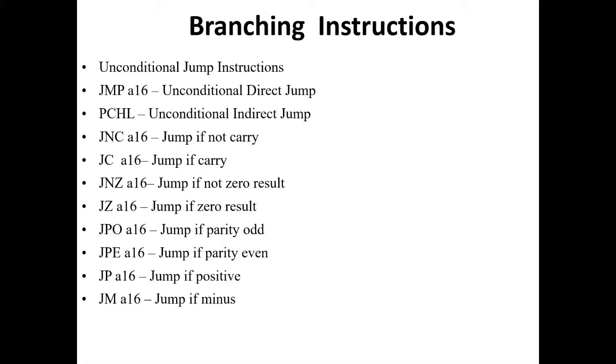Next is JPO A16, jump if parity odd. JPO is a mnemonic which stands for jump if parity odd. This instruction is used to jump to the address A16 provided in the instruction only if parity flag is 0. If parity flag value is 1, program flow continues sequentially.